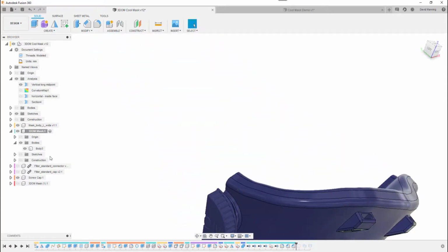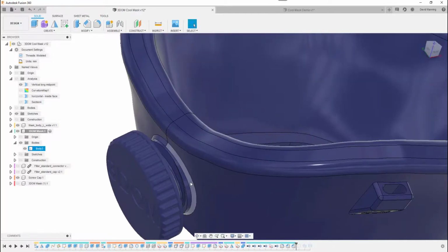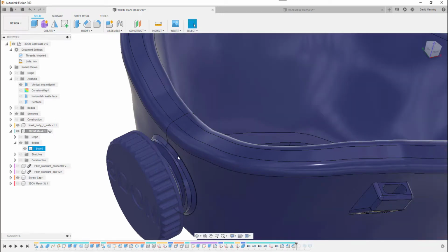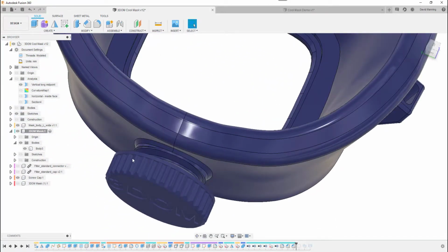on the outside. So if I take that analysis off, you can see that I've chamfered this point there. If I edit that, you'll see it's an interesting artifact because it's a mirrored function, and it's at an odd angle. It's not a circle, it's actually 2 splines. So you need to select 2 elements there to get both sides, one there and one there. Okay, so let's cancel that. So that gives you a good structural point, reduces any stresses that might occur on that join, and reduces the chance of it snapping off if it's dropped or bent. Because if this is frozen, for argument's sake, or heavily chilled, it's going to be a little bit more brittle when it's cold.